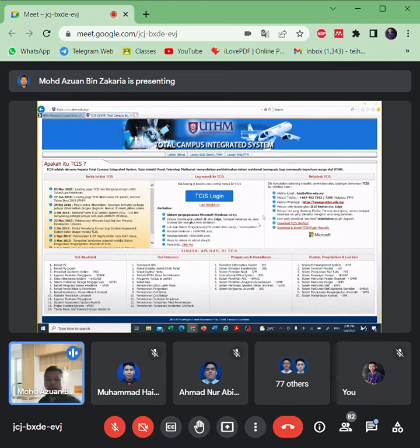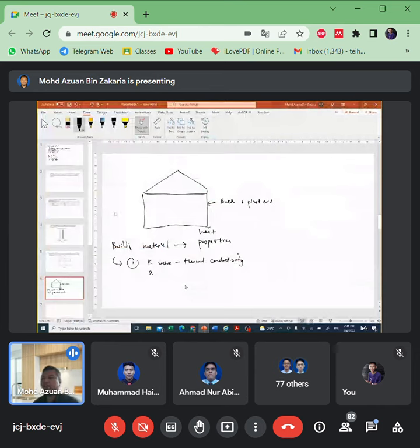So what happens is every material for the building has a K value. So brick has its K value, plaster has its K value, and then for example glass has its K or U value. So all of these building materials have heat transfer values, so we can calculate. Right. So the value depends on whether the material is a conductor or an insulator.